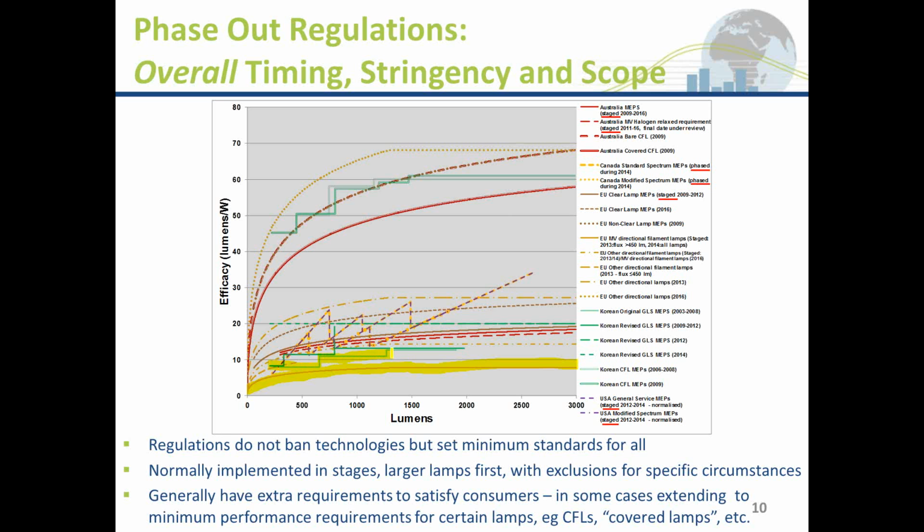As you can see, I'm drawing this. It's a stepped line, and it says from lamps with 200 to 700 lumens have to have efficiency requirements of 8 lumens per watt. Larger lamps, 10 lumens, and then those from 1200 lumens upwards are required to meet 12 lumens. So again, it's sort of reproducing this stepping as efficiency, as lamps get bigger, the efficiency requirement goes up.